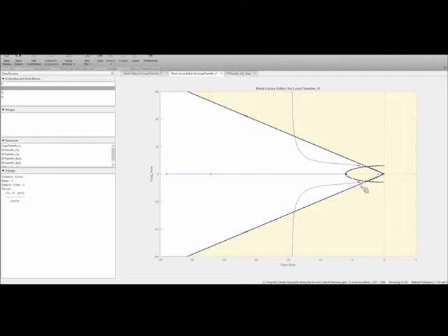So it may be really tough to see. People in the front may be able to see this, but at the very bottom right, if I hold my pointer on this point, it'll show you where that current location is. And it says -3.97 minus 5.98i. So very close, because 41 was not an exact number. It was just approximate. All right, so we essentially placed it exactly where we want the closed loop pole to be. We see that the other closed loop pole is pretty far in the left half plane.